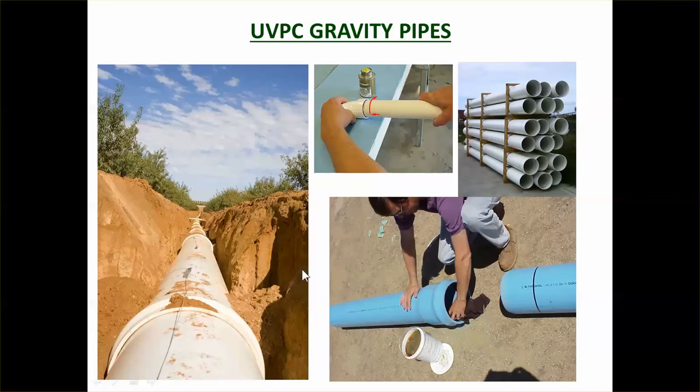That support is even more important with UPVC pipes, which really need really good lateral support. So you need to compact the sides to make sure that it doesn't start to make the egg shape when it's got loads from the top here. So you can see there's plastic pipe there. You can see they've got a little wire along there, and normally they do that, or they put a magnetic tape there, so that you can pick it up with meters from the ground surface.